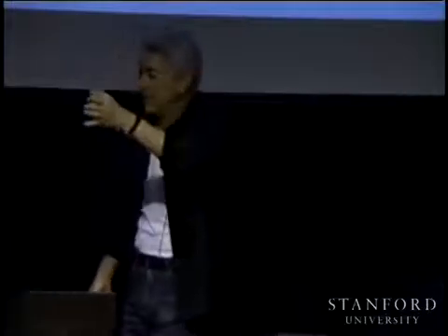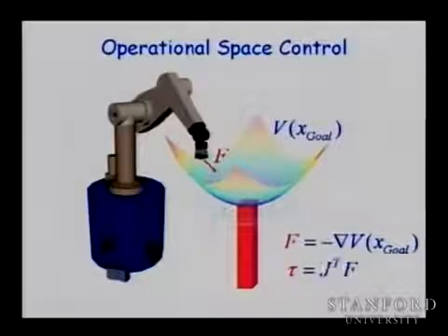So it will be torque equal to F. We need something to relate this force to the torque. J transpose F equals torque. That's it. So if you just apply a J transpose F, where F is this gradient of your goal position in X, you apply this to the system, and the result is going to be that you will move there. And it works.